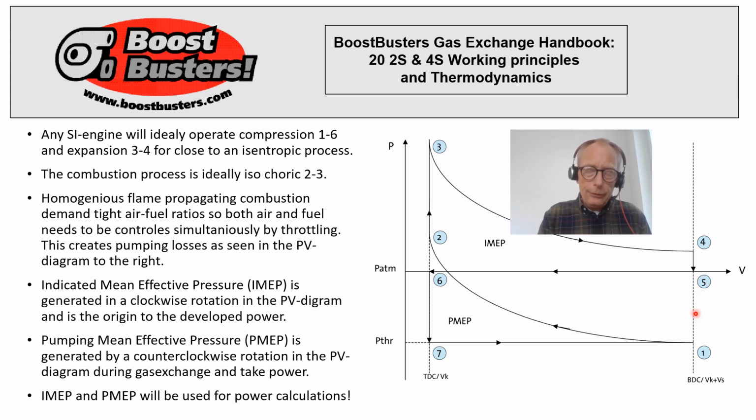So in this PV diagram, after the expansion is done, we reach the throttle pressure conditions, which could be as low as 0.5 atmospheres, starting the compression from a very low pressure. That's happening in low load conditions.